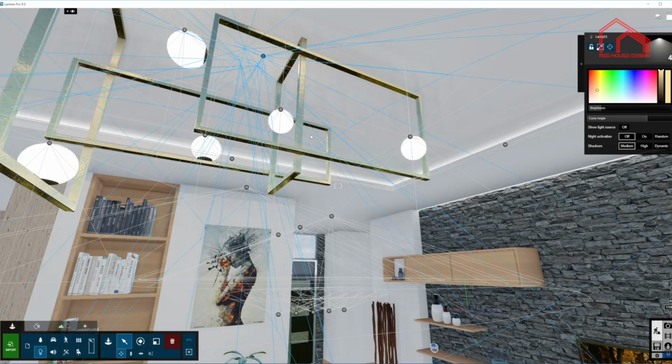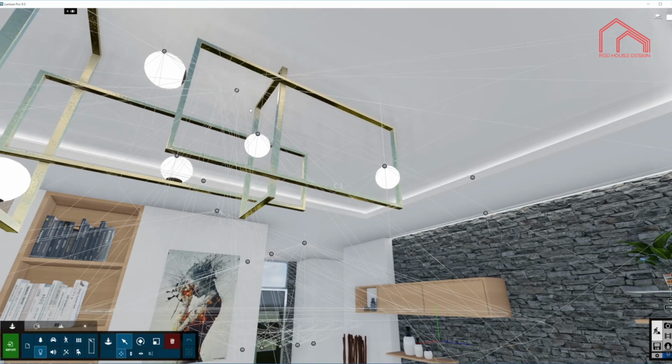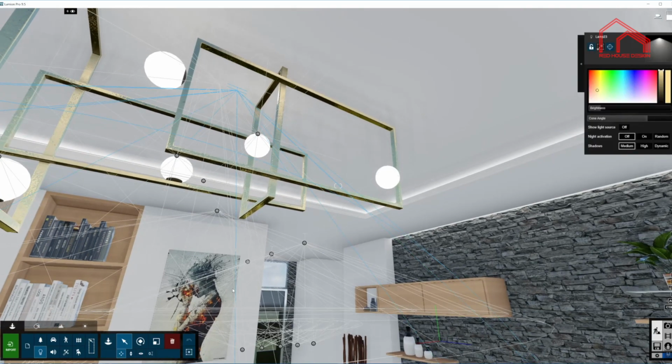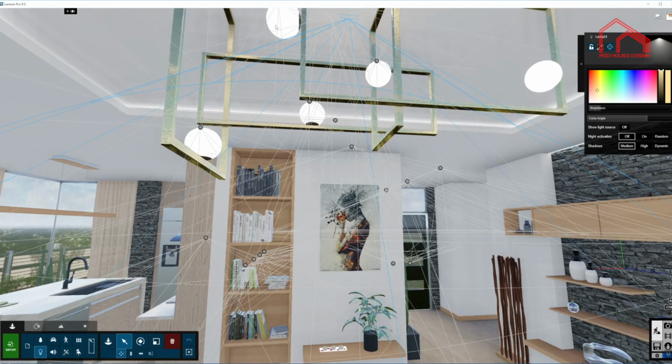So basically you select one of the lights and you aim them at a particular wall. This one is aiming at the wall just ahead of us. You can use the tool in here, the target light tool, and you basically select anywhere on this wall and the light will point in that direction. Here is the brightness of the light and the cone angle as well. As you can see, as wide as possible. So I'm basically mimicking the Omni light from these light sources. I'm matching the temperature of the light from these bulbs.